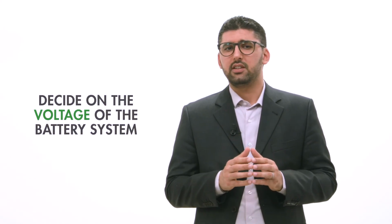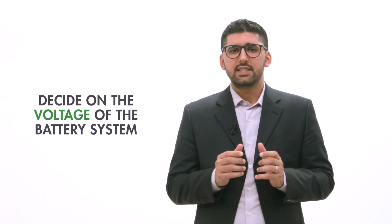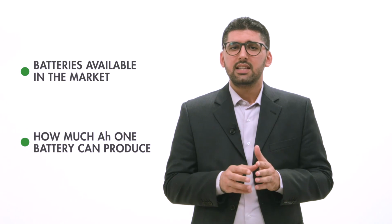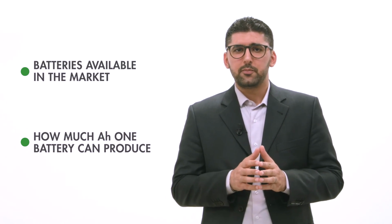Now we have to decide on the voltage of the battery system. If we choose a 48 volt system, this means we need 27 kilowatt hour divided by 48 volt. That gives us around 600 ampere hour out of the battery system. Now it depends on the batteries available in the market and how much ampere hour each battery can produce.